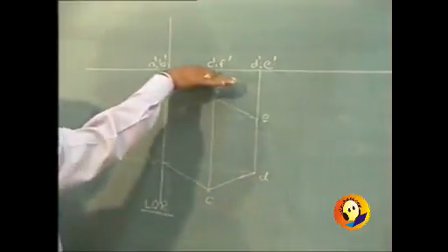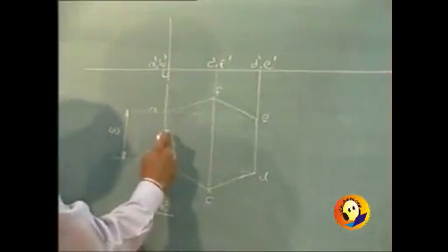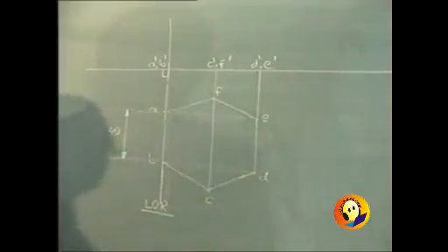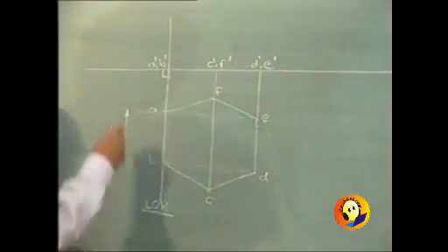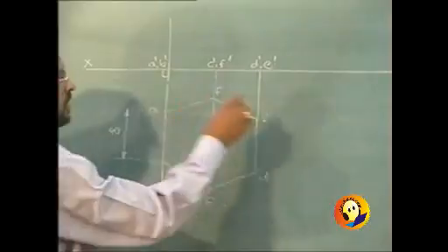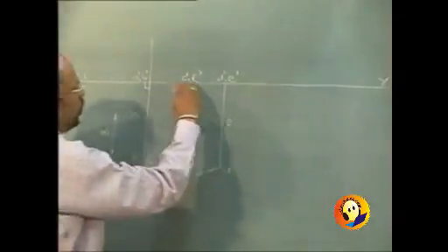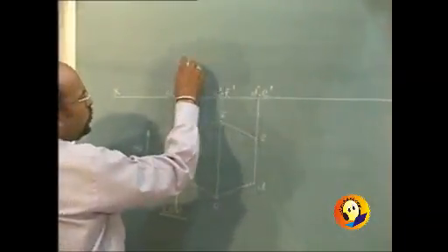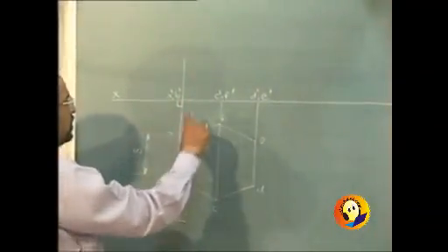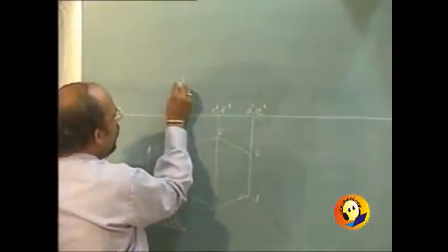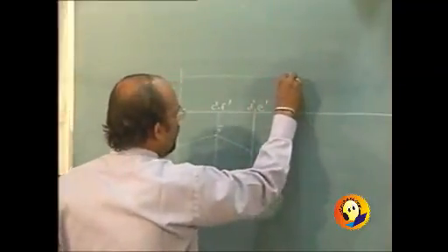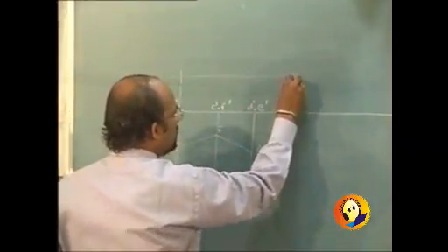And now as we start rotating the line view, it is given that the side opposite to the side in HP, that means side DE, should be at a distance of 30 mm from HP. Of course, in the elevation, the XY line itself will be considered as the horizontal plane, and this D dash E dash point should move up and achieve the height of 30 millimeters, so we can draw a line at a distance equal to 30 millimeters from XY,